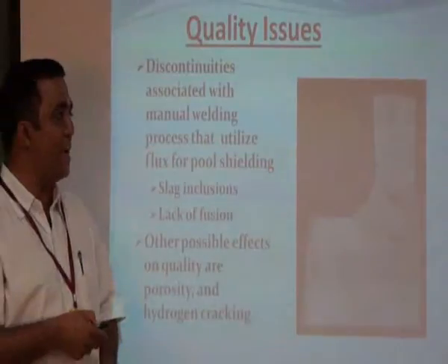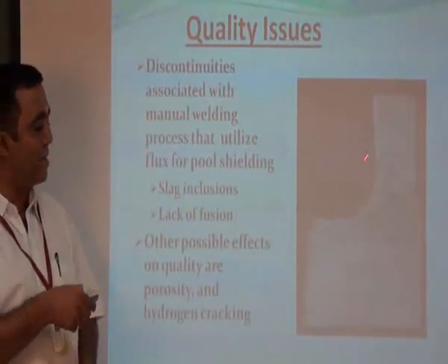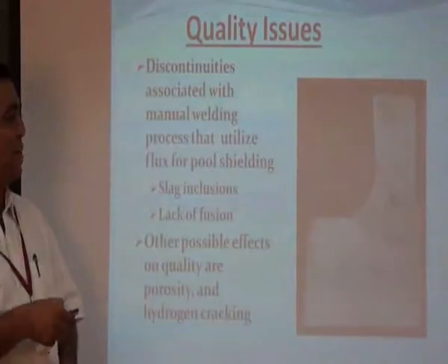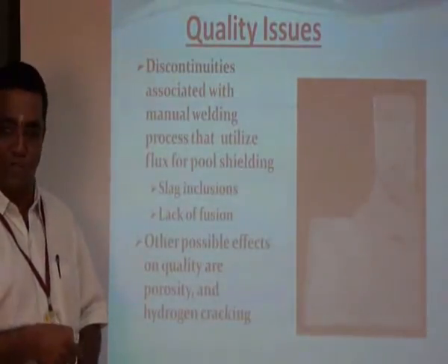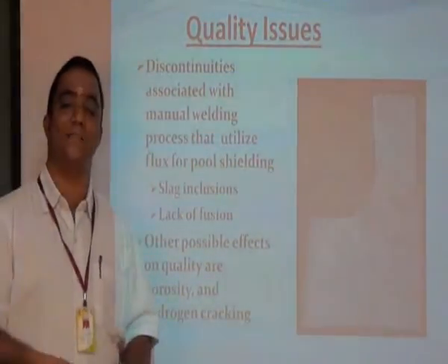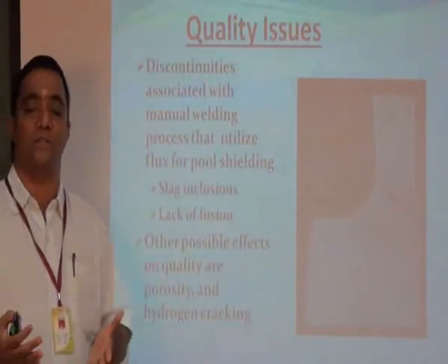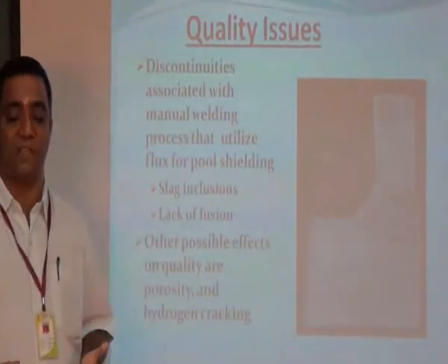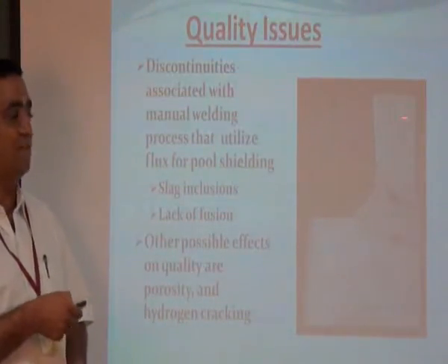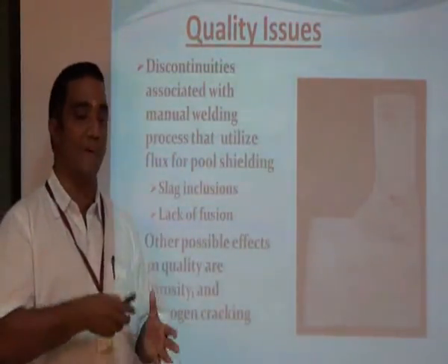Sometimes these impurities get in along inside this weld pool, and they form what are called slag inclusions, and these inclusions serve as a crack. And after the weld is solidified, you will be able to see the cracks if these impurities are embedded inside the solidified weld metal.